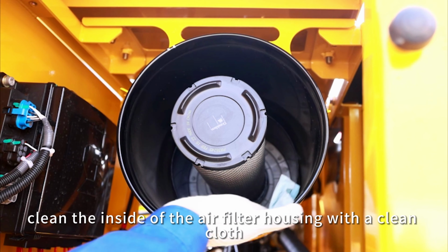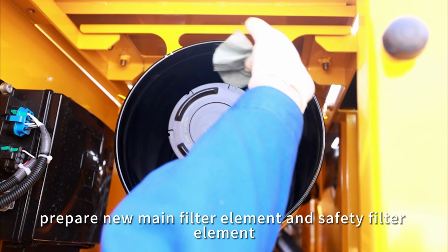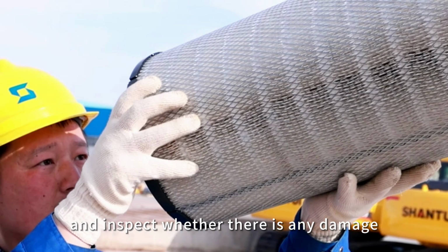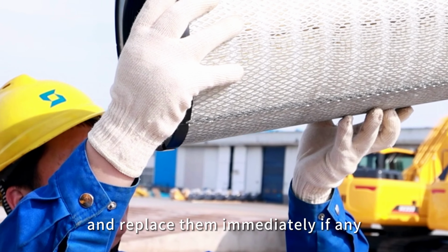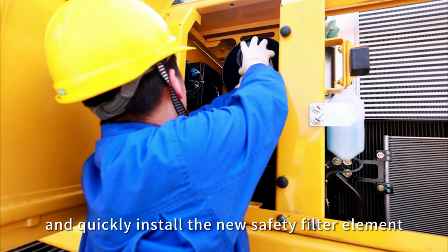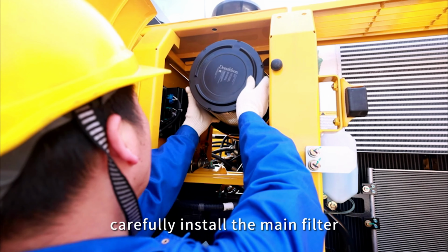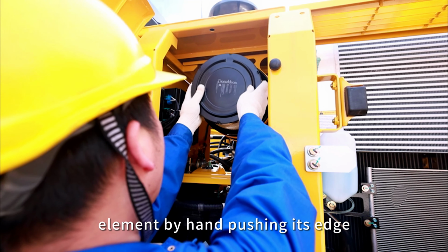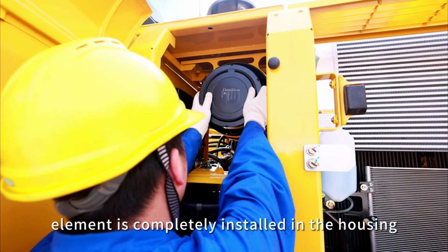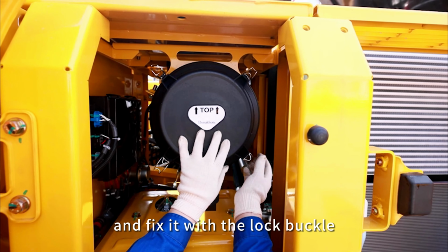Clean the inside of the air filter housing with a clean cloth. Prepare new main filter element and safety filter element, and inspect whether there is any damage, and replace them immediately if any. Remove the safety filter element, and quickly install the new safety filter element. Carefully install the main filter element by hand pushing its edge, and confirm that the main filter element is completely installed in the housing. Install the end cap on the air filter housing, with the top arrow on the end cap facing upward, and fix it with the lock buckle.